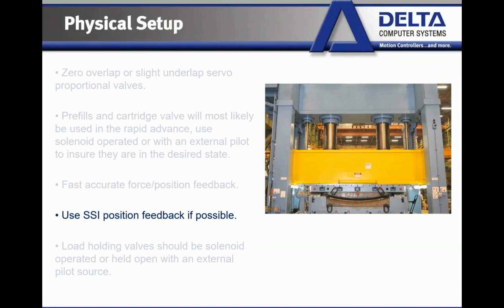It works great, high precision, low noise, and if for some reason, maybe cylinders are undersized and you're having problems with oscillation, and we have this high quality feedback, we're able to use what we call the second derivative gain. If you'd like to know more about this, again, please use that question box. We can talk more. But using this gain, we're able to compensate for systems that aren't optimally designed.